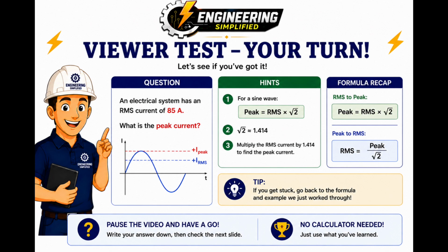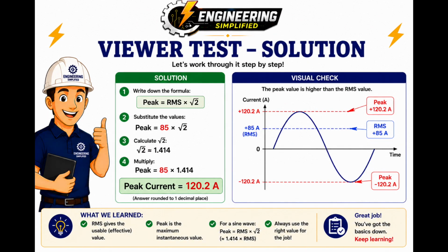Now it's your turn. An AC circuit has an RMS current of 85 amps. What is the peak current? Pause the video here if you want to work it out yourself. Remember, for a sine wave, peak equals RMS multiplied by the square root of 2. Ready? Let's work through it.